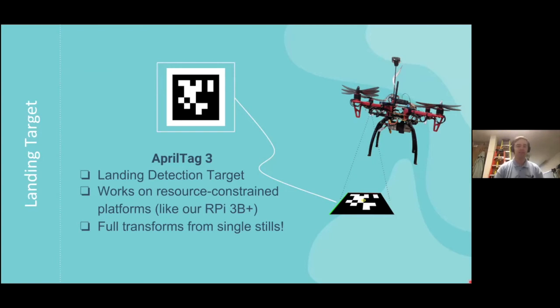It locates rectangles in the environment. It reduces down the code by a Hamming scheme compression algorithm, error correction algorithm, sorry, and then determines whether that code is the specific tag we're looking for. And using all of these stages in hours and hours of testing, we've only had about 32 misdetected tags, and every one of those tags had a different ID from the one we were intending to land on at the time, meaning they did not affect our system whatsoever.